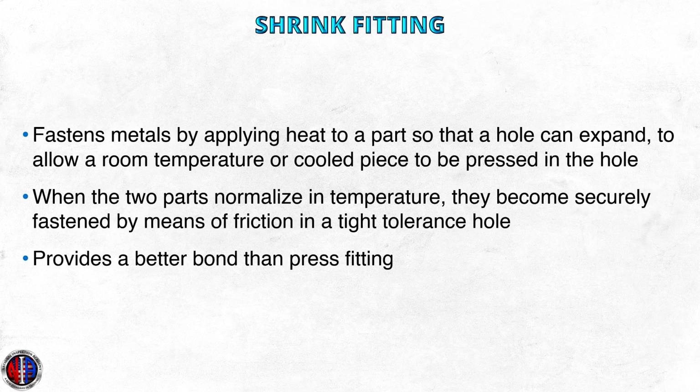Shrink fitting. Shrink fitting is another means of fastening metals by applying heat to a part so that the hole can expand to allow a room temperature or cooled piece to be pressed into the hole. When the two parts normalize in temperature, they become securely fastened by means of friction in a tight tolerance hole.